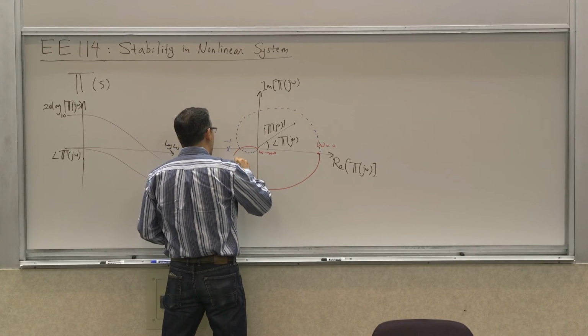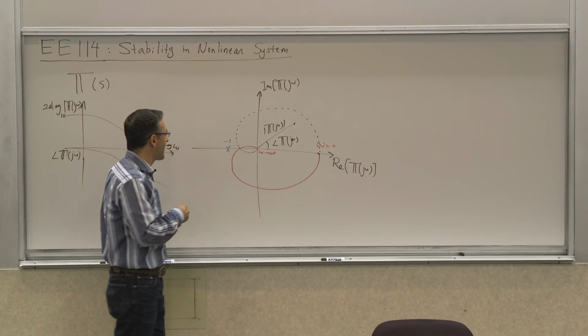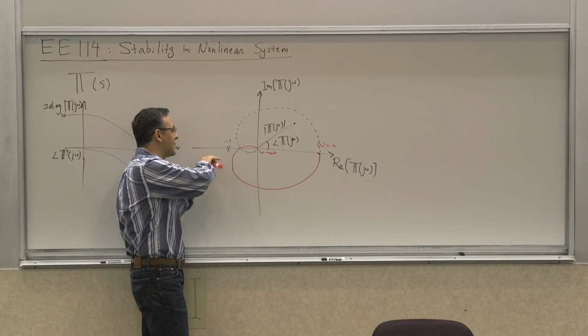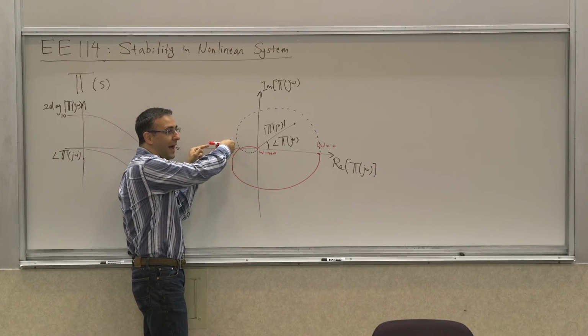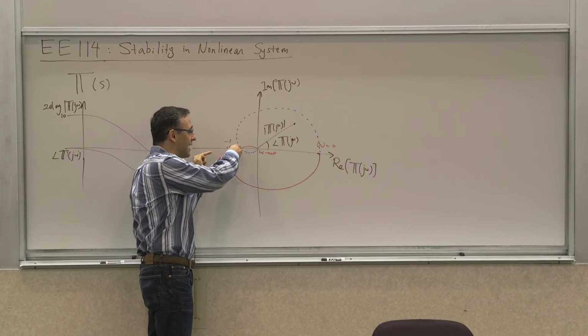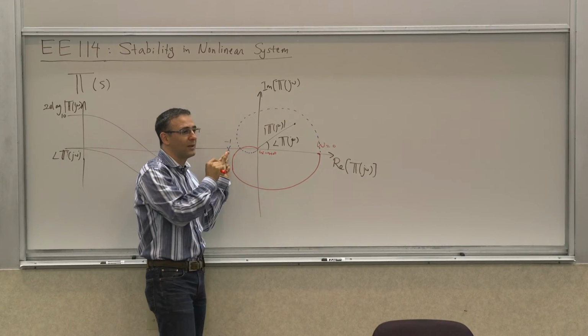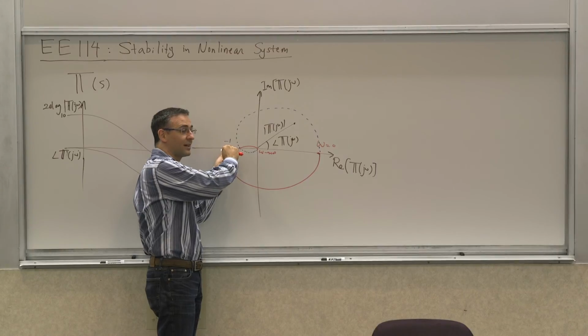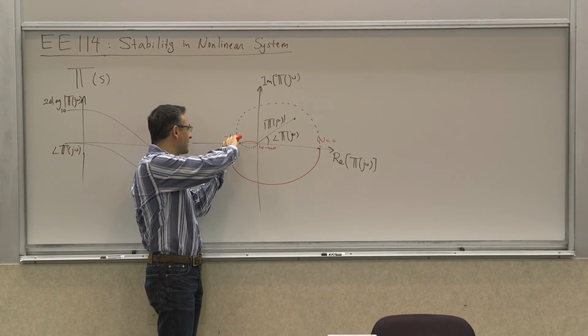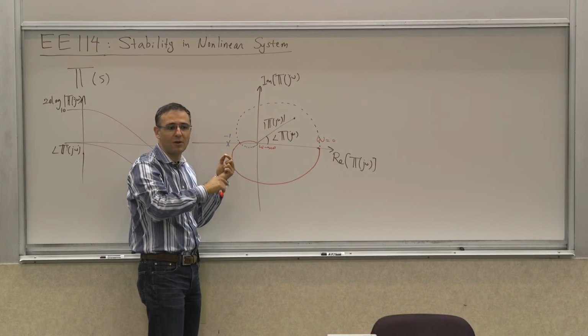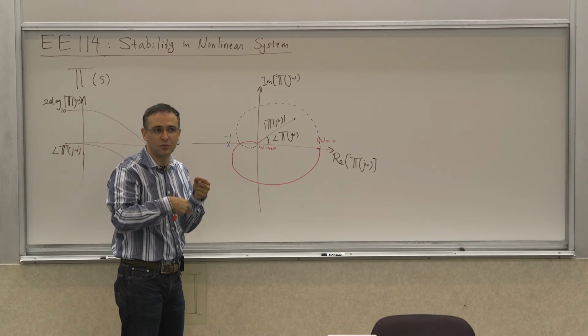So in this case, the criterion for encirclement is that if you sit at the point -1 and look at it, how many full turns do you have by the end of the cycle? One way to think about it is that you have a little string or rubber band, and at the end of the process, when you start from one point and end up at that point, if your rubber band has twists, how many twists does it have?